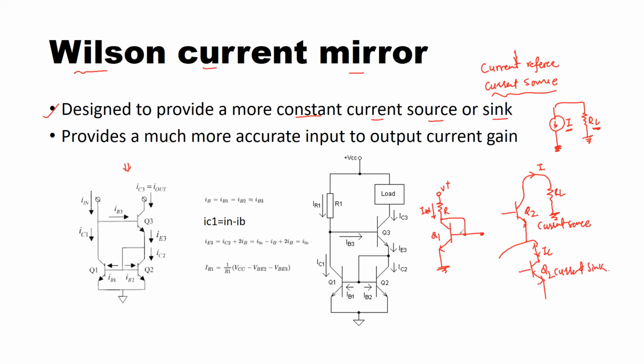And because of the way this transistor is connected, it produced a junction voltage, the emitter base junction voltage of VBE. So it acted as a current to voltage converter. All right, and then we use this voltage source, which is VBE, to bias another transistor, and we call it Q2, and that's it.